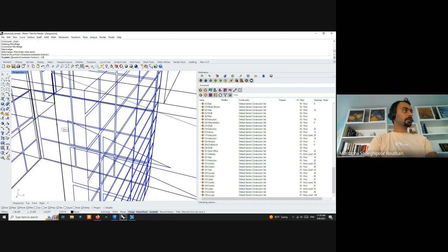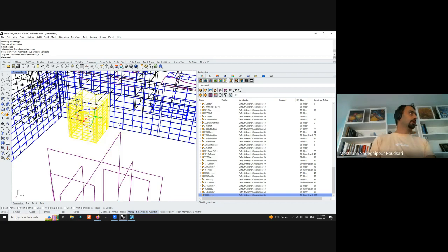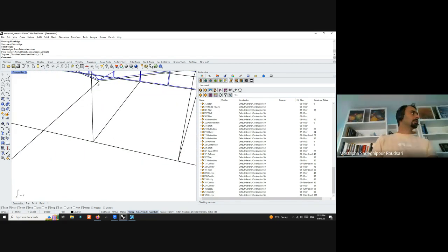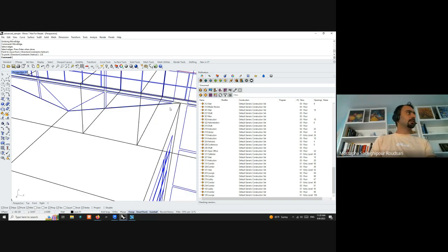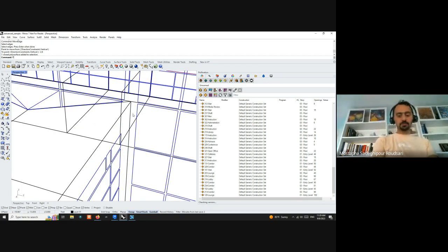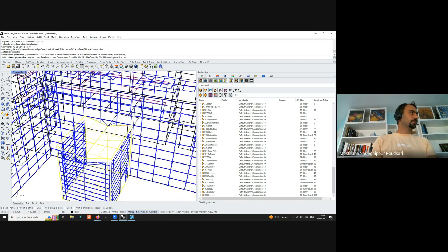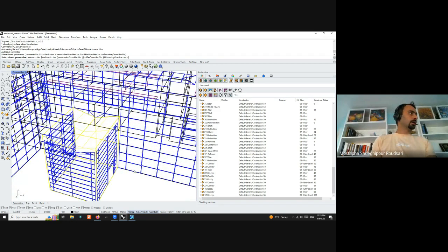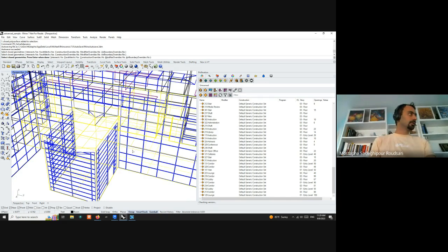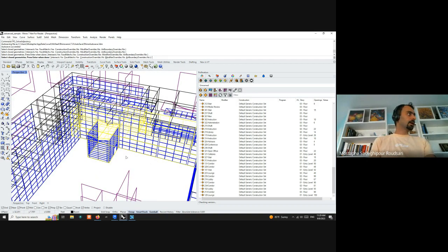Minus 2.6. And here we go. So the model is here. I can see all this. One other thing I'm going to do, because now I changed this, I have to run the solve adjacency, so the adjacency between this room and that room gets updated. So I do PO solve adjacency, and I'm going to select both of these rooms, and then press the space. What it does is basically run solve adjacency, so it split all the faces and everything that needs to be done.